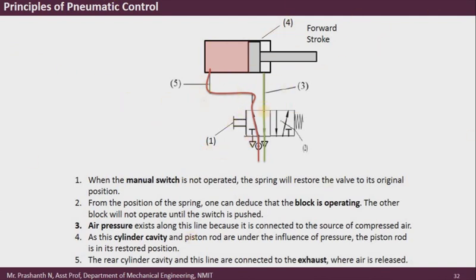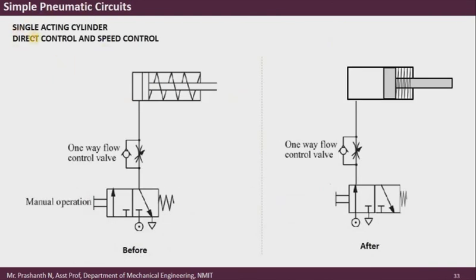These types of cylinders are very widely used in various applications. We will look into a couple of applications where such cylinders are used. First, let us take a simple example of direct control and speed control of the single acting cylinder.